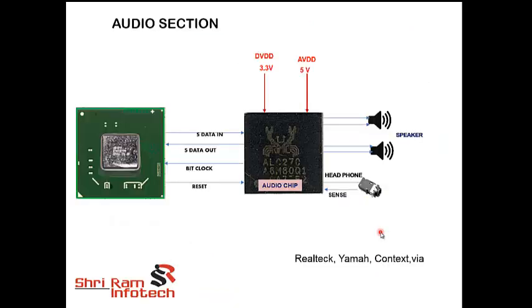So the next peripheral we are going to check is the audio section. When you have a laptop and it's not giving audio, what you have to do is first check the drivers. First the driver should be perfect.